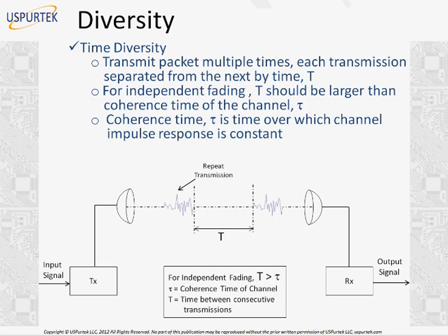You know, because of this fading, environmental fading, the fading can happen not just because of reflection or multiple signals received, but the channel parameters can also change. If it is a rainy day, you will have a different channel response. If it is a sunny day, you will have a different channel response. Or from time to time, they can change. So we define a coherence time, the time over which we know for sure that the channel impulse response is constant.